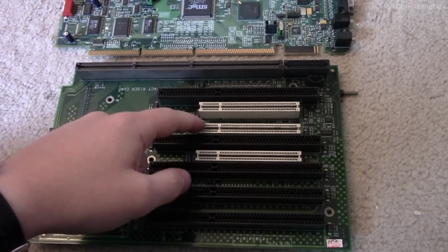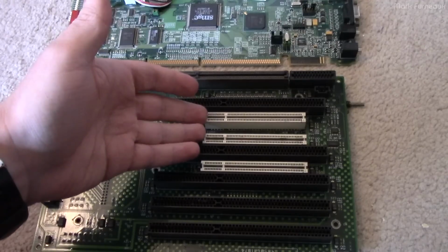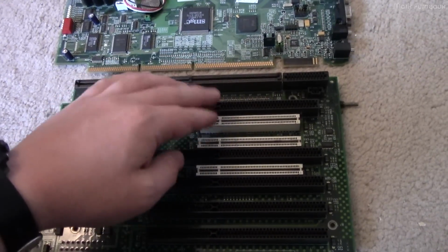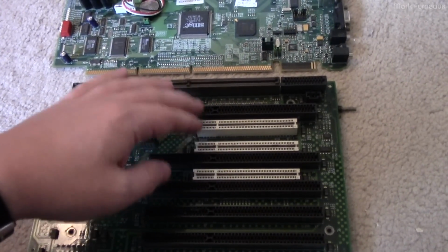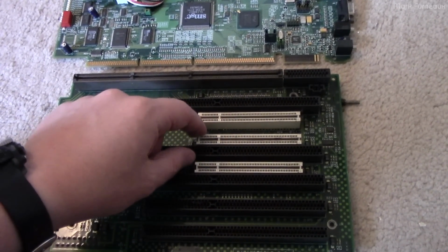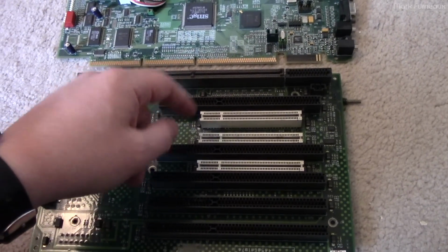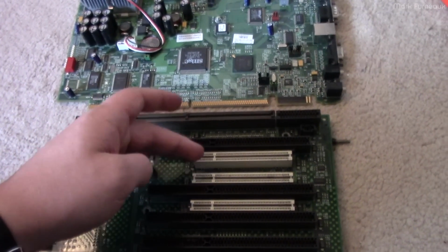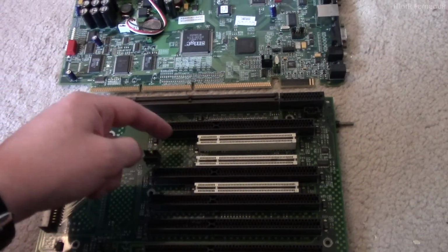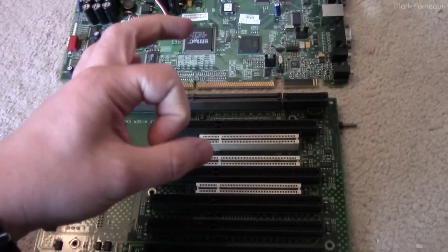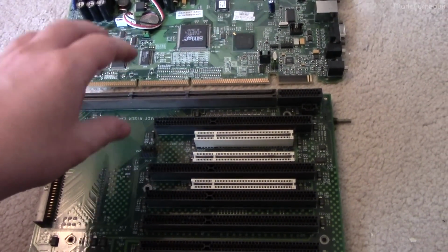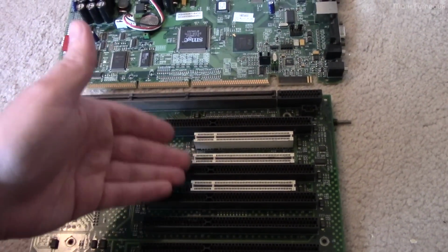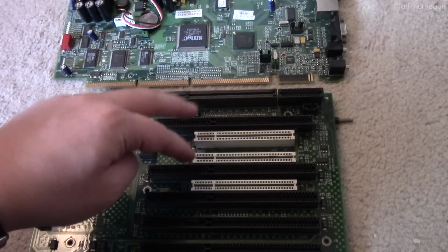But in order to get those kinds of boards, there is a technology that was developed by the PCI Special Interest Group, I think it's the PCI SIG. They're basically the body that oversees the standardization of PCI and PCI Express. They defined a standard for bridging PCI Express to PCI. So if you had a new system that you needed to put PCI devices on, which is very common in industry, you could get some sort of chip that would create a PCI bus and connect it to a PCI Express interface. And so those motherboards that had the combination of slots have one of those chips on board.